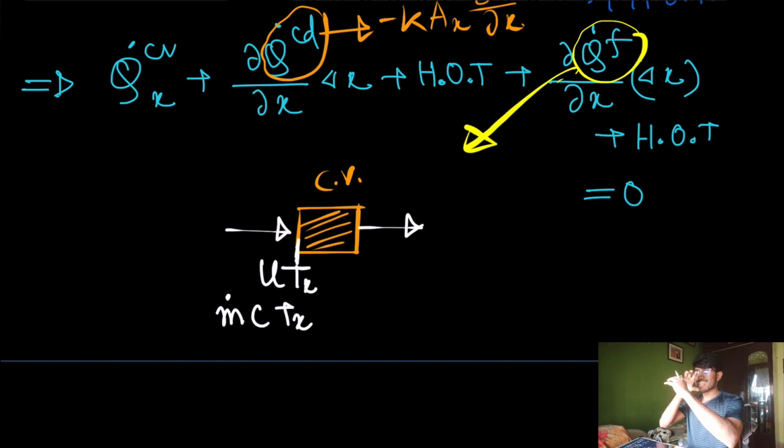Now at this position where the rod is leaving the control volume, the rod is having a different amount of energy, okay. So when it is leaving from here, again because of its mass flow rate, it will be leaving the control volume with a particular amount of energy. So that is what I am talking about here, and that I am calling flow energy, Q dot F, okay.